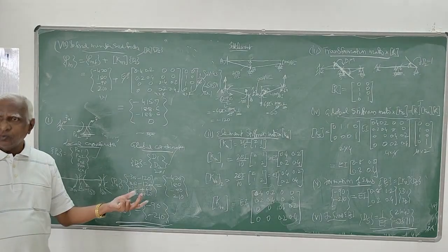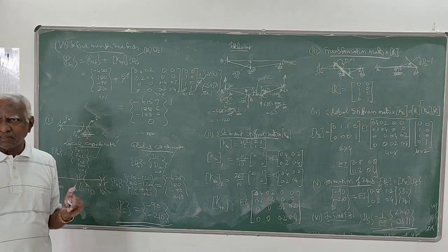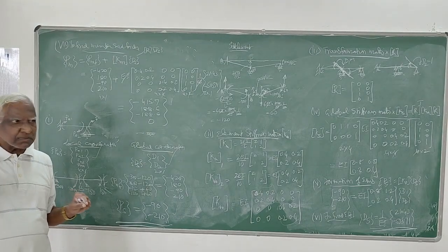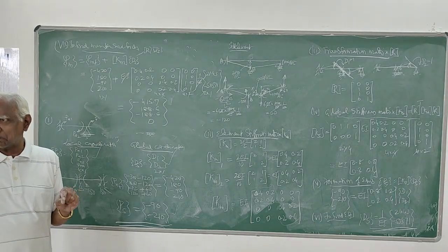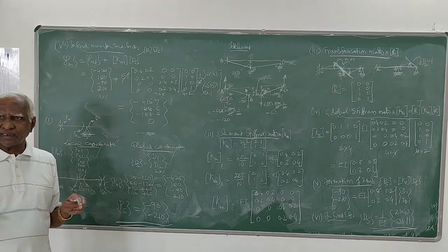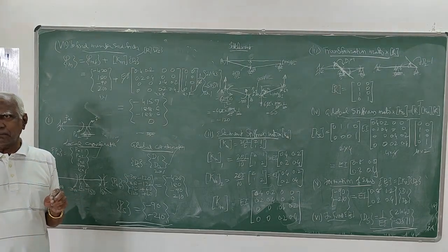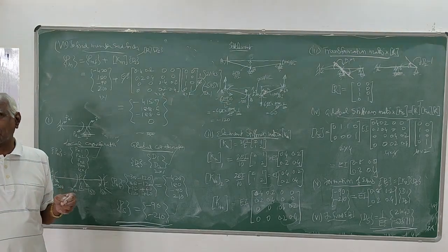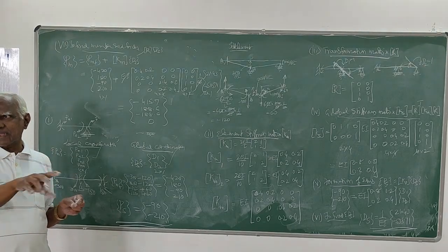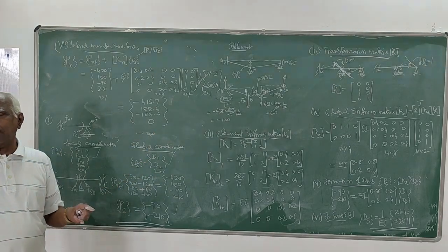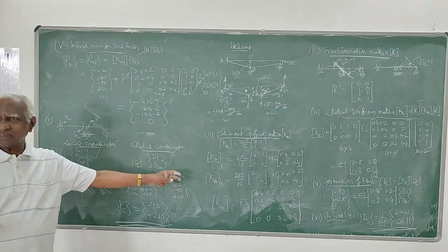Then how to formulate the stiffness matrix, the element property, that is, defining the strain displacement matrix, constitutive matrix, stress strain relationship. Taking from elasticity, there is a definite procedure, step by step, wherein we can program it on a computer in an easy way. That's why that method has been adopted. Easily it can be programmed. But here it is difficult to write a program.